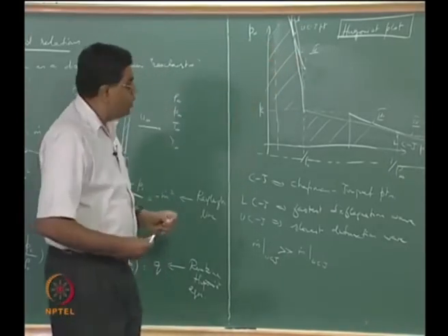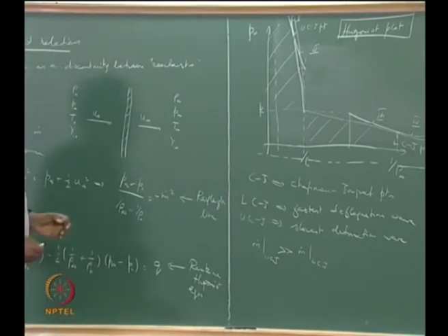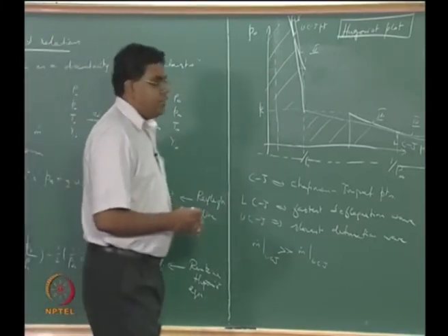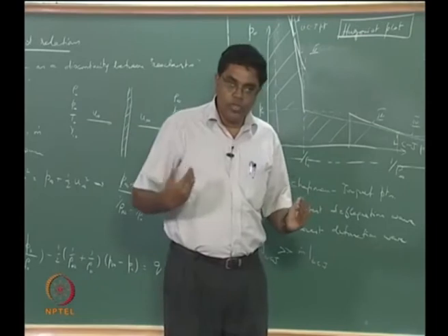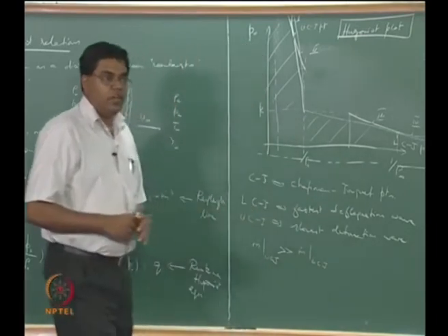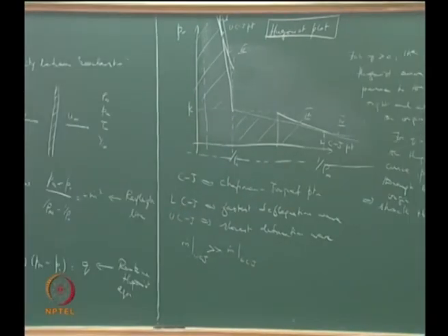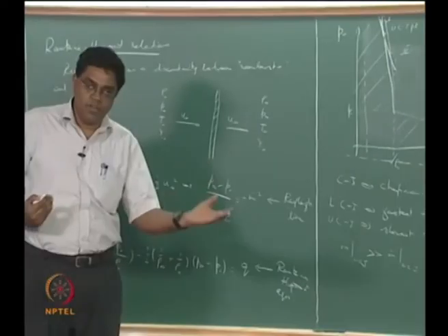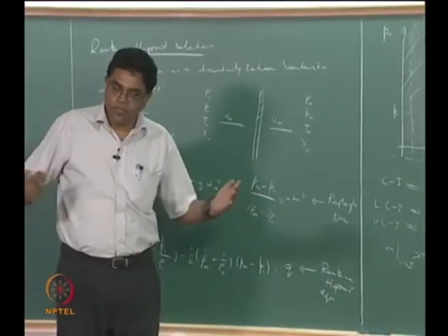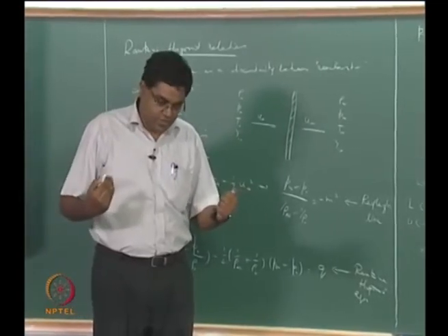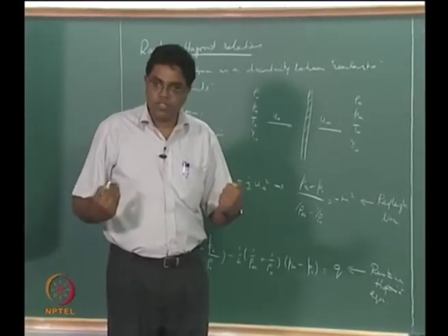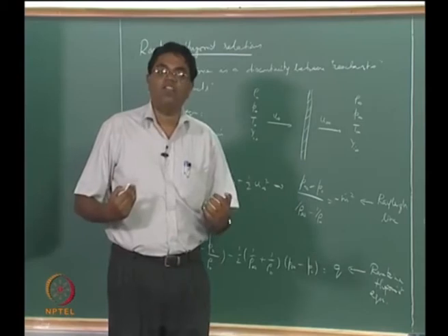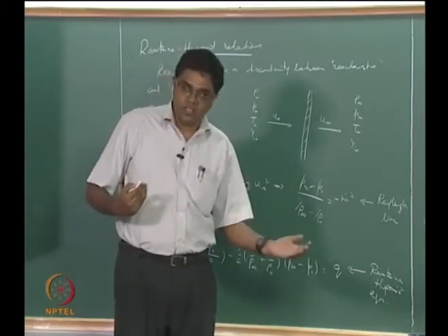Okay, what we will actually find is when you now have a flow that is going through a detonation wave, just like in a normal shock, you should expect that if the flow is approaching the wave at supersonic speeds, if the shock is very strong, you should expect the flow to actually become subsonic all the way. That's a mark of its extent of compression. So if it has been compressed a lot, the flow also gets decelerated, right.